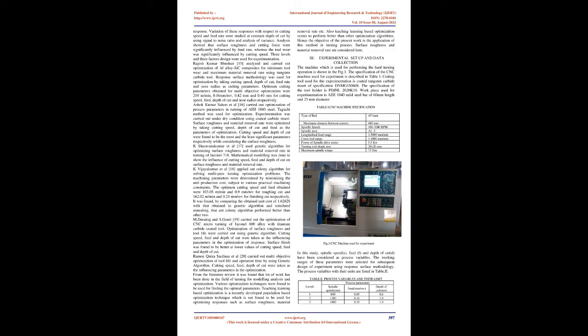Aman Agarwal et al. [10] carried out multi-response optimization of CNC turning of AISI P20 tool steel using response surface methodology and desirability function. Tool life, surface roughness, cutting force, and power consumption were used as the responses for optimization by taking cutting speed, depth of cut, feed, and nose radius as parameters. Experimentation was carried out using liquid nitrogen as coolant.